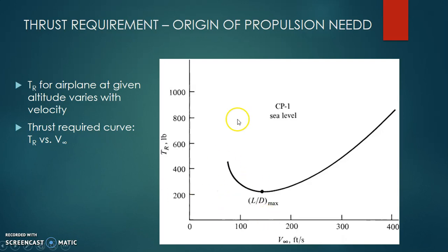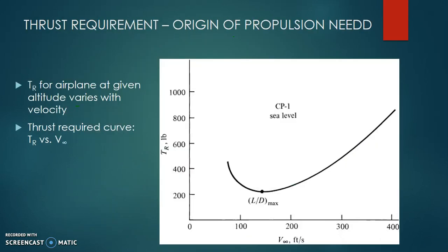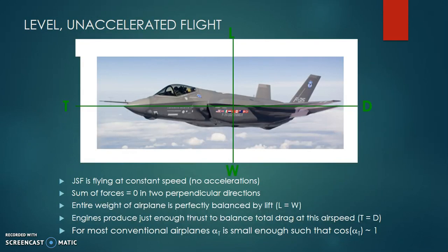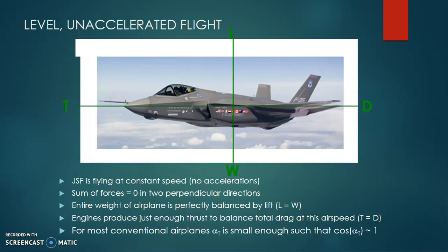As the velocity increases, the thrust actually keeps reducing, which means there is a tendency where the high thrust actually starts coming down. This is the case because at these particular points, the drag and the lift are not yet balanced. So you remember these equations. Now when you are not in cruise mode but in different increasing velocity maneuvers, the drag performs as a square function of velocity, and so does the lift.